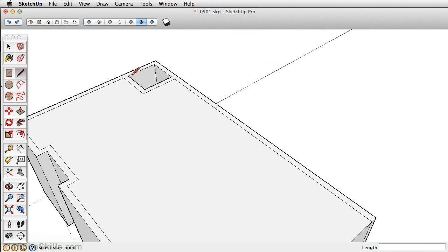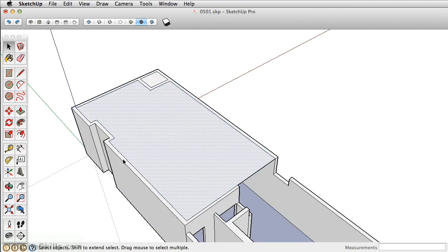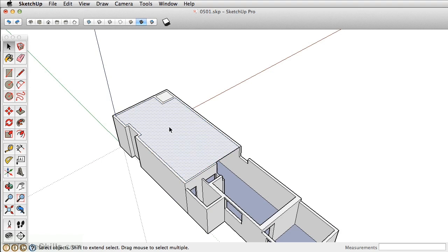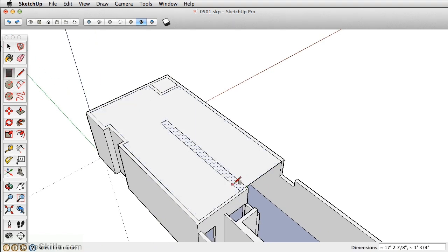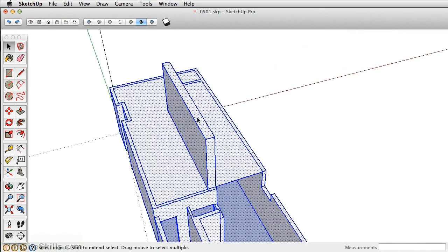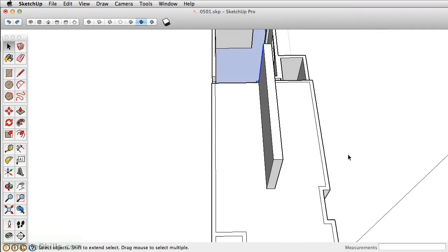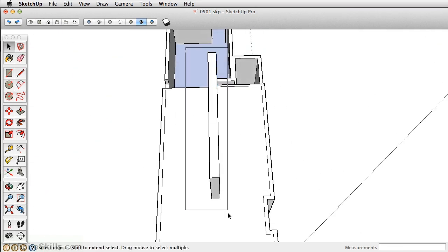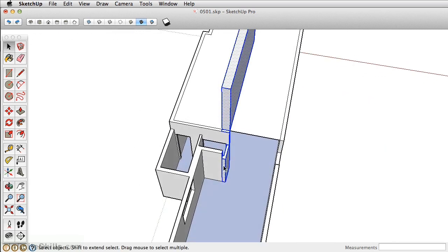and I begin creating the walls of the second floor or even cut out some of the elements, all this geometry is touching. If I ever need to move anything, say we have a wall here, I pull this up. If I ever need to move this, it's very difficult because everything is touching. And it's really hard to select if we go left to right when we select this. We're also selecting items on the first floor. And we don't want that.